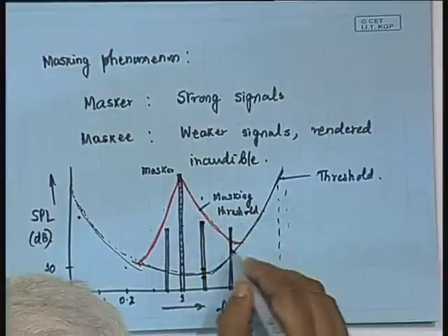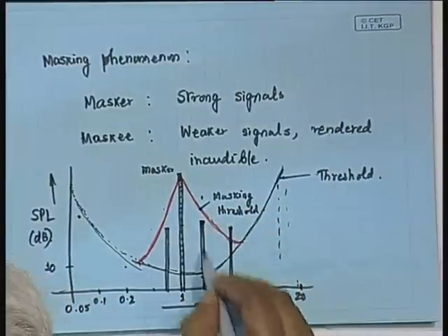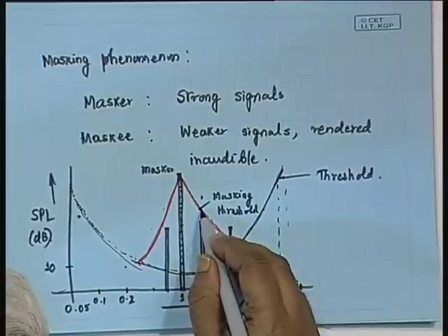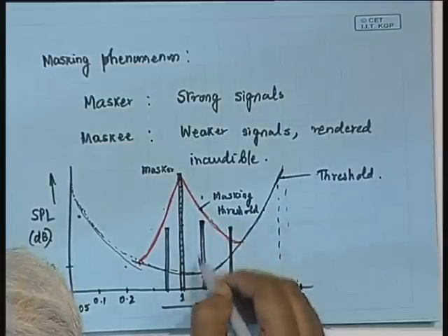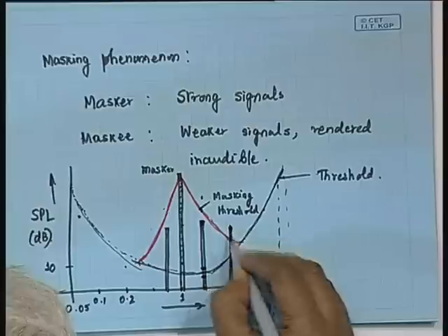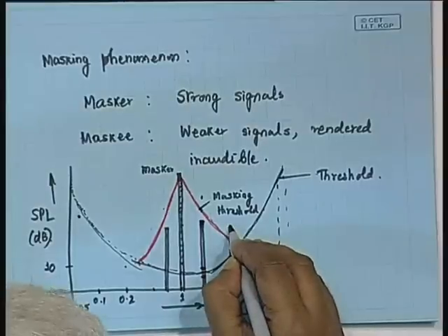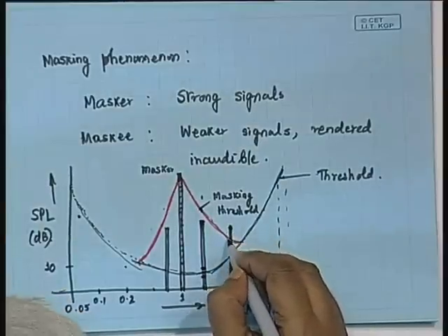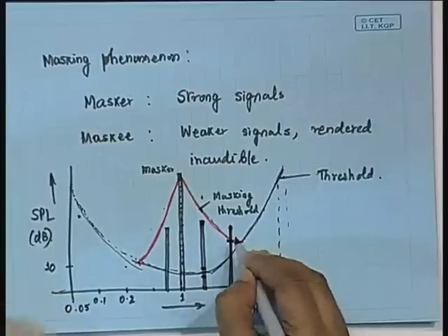Whereas, say this much quantization noise will be inaudible for this frequency, but at this frequency, if the quantization noise is this much, then it gets audible. So, at this frequency you have to bring it down, you have to allocate more bits. So, close to the masking threshold, or rather closer in frequency to the masker, you can afford to have a lesser number of bits.